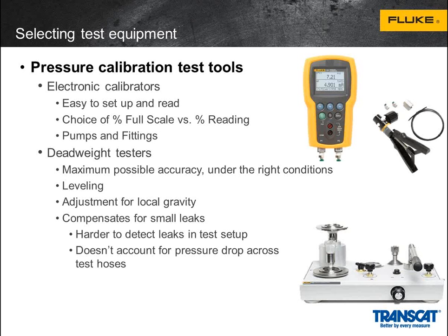Two other small things. Because the unit will compensate for a small leak, which is actually a benefit when you're in the lab, it's actually a problem when you're in the field. It's harder to detect leaks in your setup, and obviously when you're setting up and tearing down pretty frequently, it's easy to introduce leaks. It also doesn't account for the pressure drop in your test hoses, which means that you have to calculate that yourself.